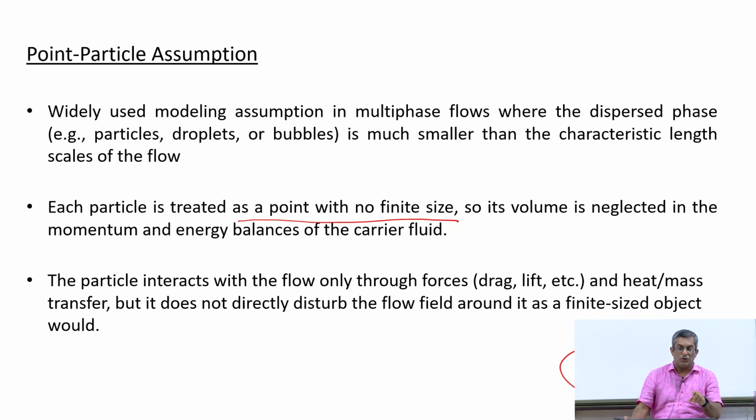That is why this is useful when the size of the particles or bubbles is much smaller. If the size of the particles and bubbles is larger, then you can have this kind of effect. And in case of bubbly flows, for example, you can have the virtual mass term or the added mass term also becoming important, or the undisturbed flow term. All these factors will become important. So, in this model, we basically neglect the volume of the particle.